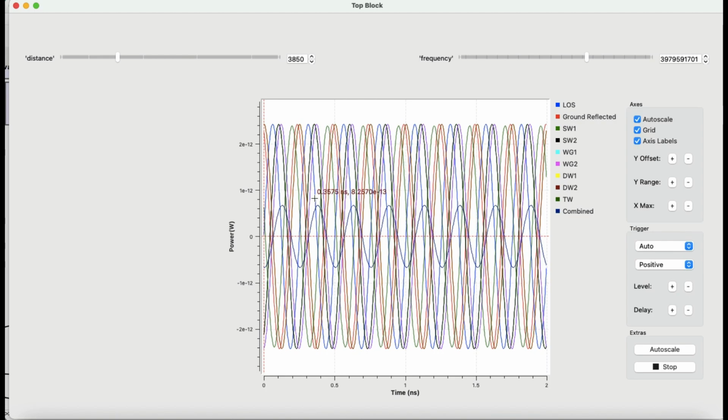After 10 different waves are being reflected from everywhere, this is the type of signal strength that I would encounter in terms of power. So this is how much power is going to be received. So this is somewhere around a picowatt value. So my signal strength is quite down, and picowatt or nanowatt corresponds to roughly, I'm saying roughly, somewhere around -100 dBm or something like that. So this is the best way to visualize your multipath fading using GNU Radio.